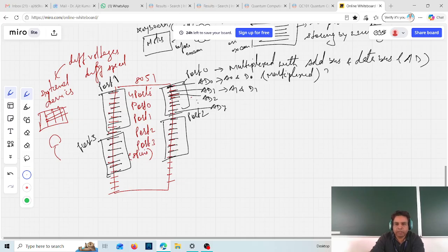So in these 8 pins we have utilized A0 to A7 and also D0 to D7. If I had not done this multiplexing, a total of 16 pins would have been wasted. Instead, I have utilized only 8 pins.